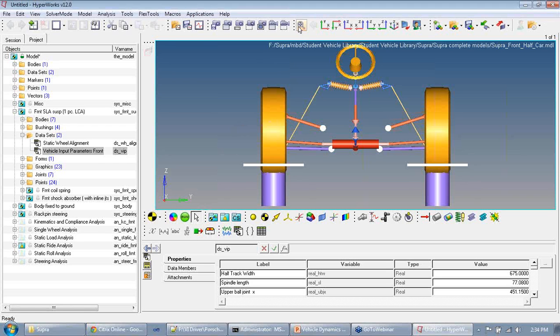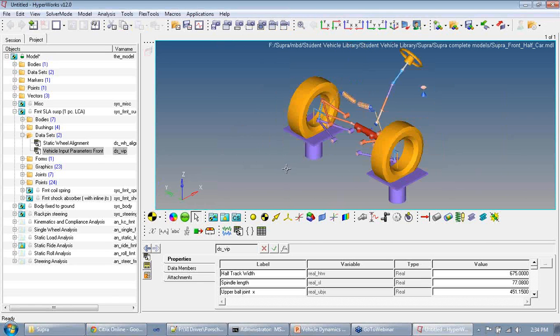The question I already have is where does the origin lie and can we move it? As I said, by default we have assumed that the origin is somewhere in front of the car. Can you move it? The answer is yes, but please make sure that the XZ plane is the plane of symmetry and X points towards the rear of the car. This model is a template model that has been prepared with this convention in mind. So changing the coordinate system to something else will not be a very easy task. It's a tedious process. I would highly recommend that you keep the XZ plane as the plane of symmetry, but you can have the origin anywhere you choose on the XZ plane.